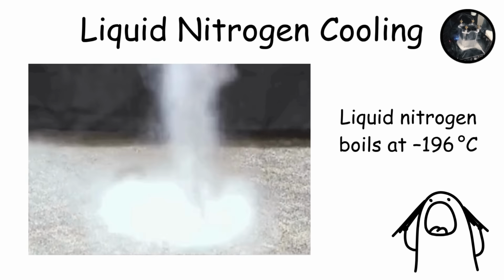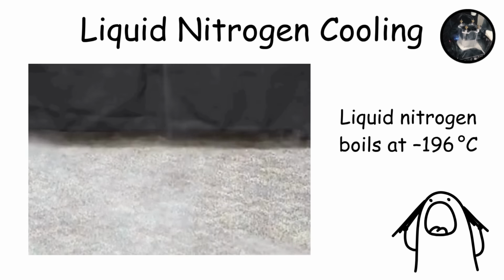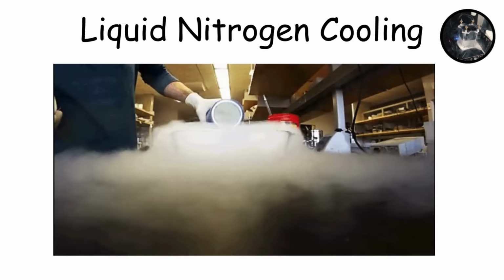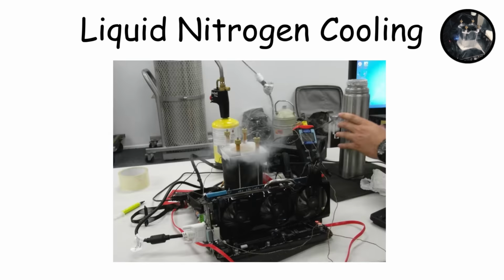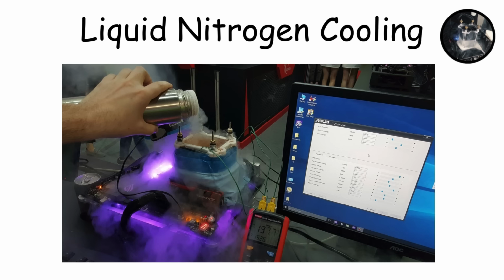Liquid nitrogen boils at -196 degrees Celsius, and when poured into a metal pot mounted on a CPU or GPU, it rapidly absorbs heat and evaporates. That drop in temperature allows for massive overclocks far beyond what traditional cooling systems can handle. There are no pumps or radiators, just pure cryogenic liquid and a carefully insulated setup.